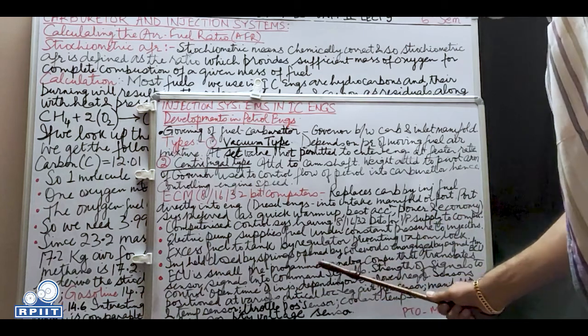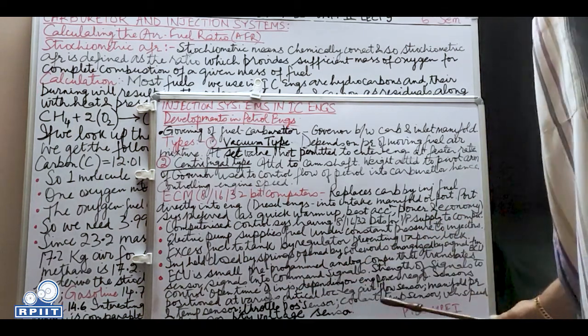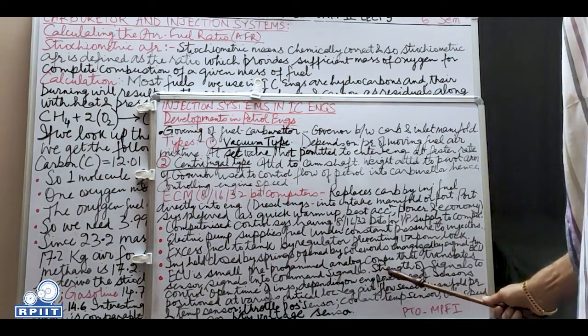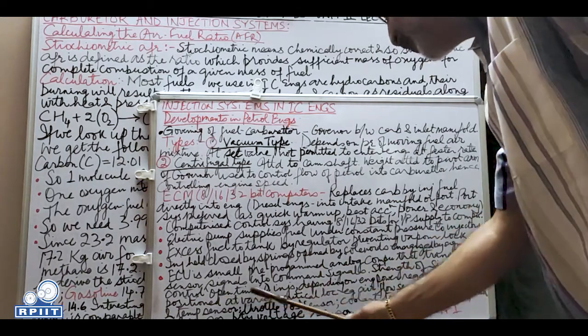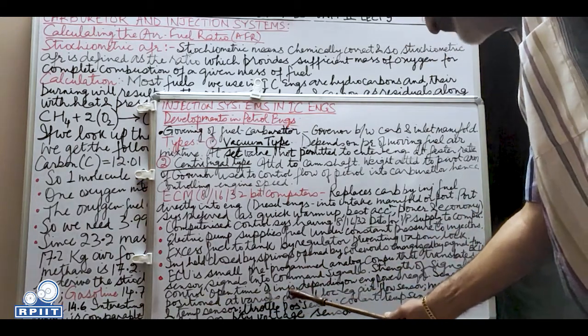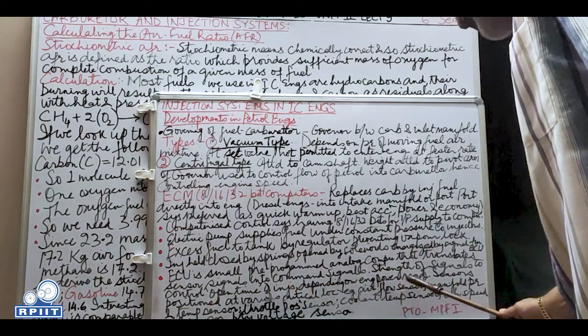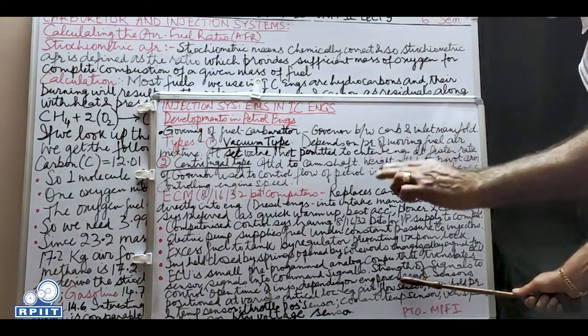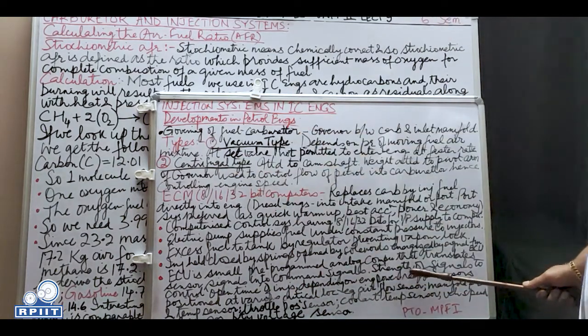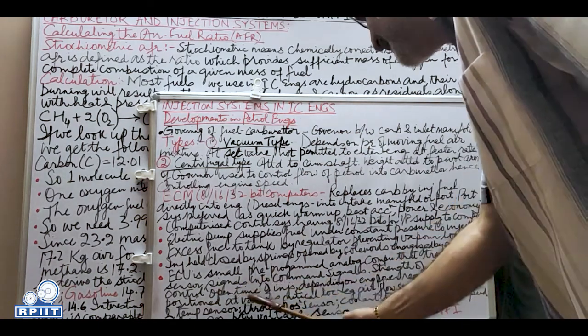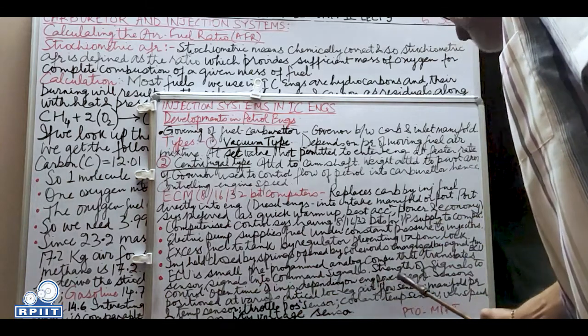A command signal goes to the solenoid; the strength of signals controls the open time of injectors, as I just mentioned, depending on the engine power required. More power required, the opening will be more, and more petrol will be injected. Sensors control the open time of injectors depending on the engine power.